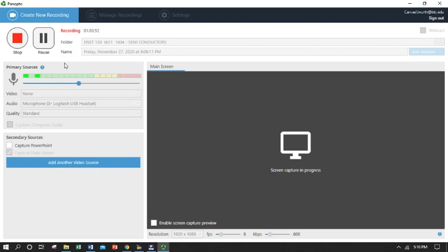Second, we can arrange our resistors and our supply voltages to effectively make us independent of beta, such that if beta changes while the circuit's operating, we don't change our collector current. And we've also seen how feedback can give us an extra measure of stability by making base and collector current inversely related the way that our circuit is arranged and operating. So for our next lecture and our next chapter, Chapters 6 and 7, we'll start evaluating what happens when we put an AC signal into our base and actually start running these circuits as amplifiers.